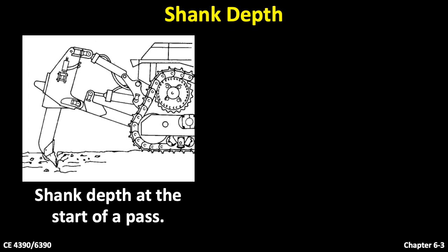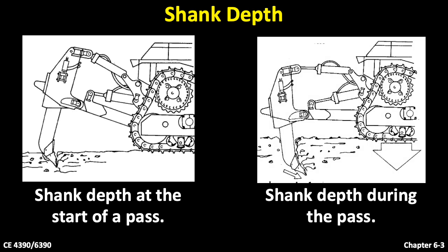The shank depth is typically low at the start of a pass. Then you need to gradually penetrate the shank deeper into the rock until a desired depth is achieved, and remain at it during the pass.